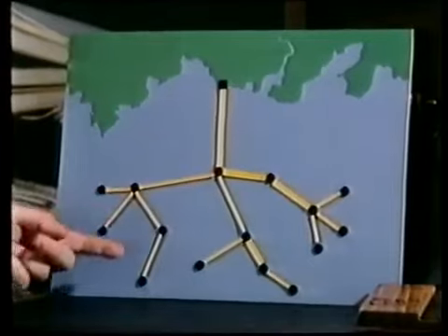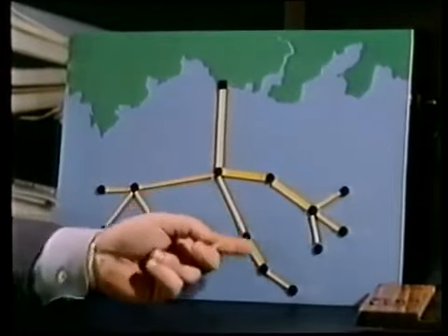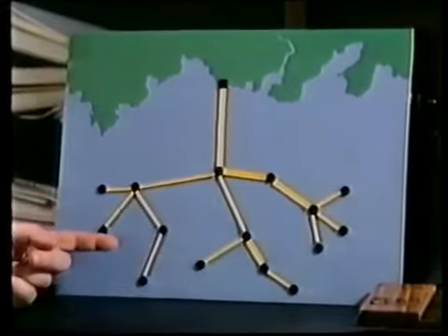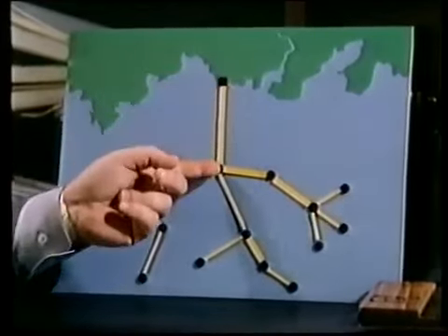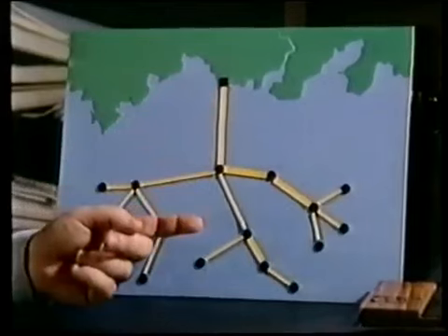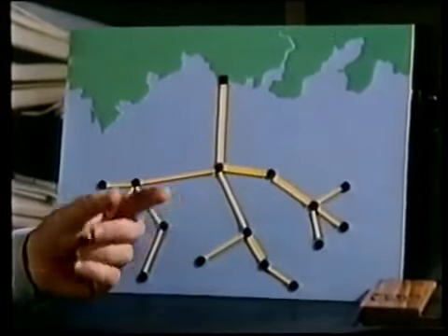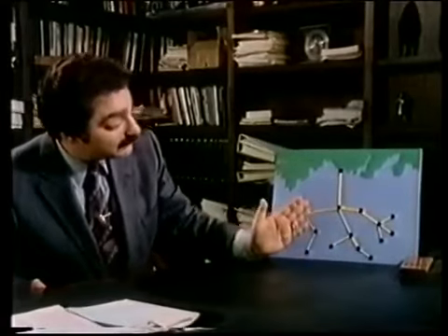And we could do that for every element and path on this tree, thereby at the end arriving at a single branch with an equivalent set of diameters and costs associated with them. The practical part was to eliminate huge numbers of diameter combinations without ever examining them. That was the real breakthrough.